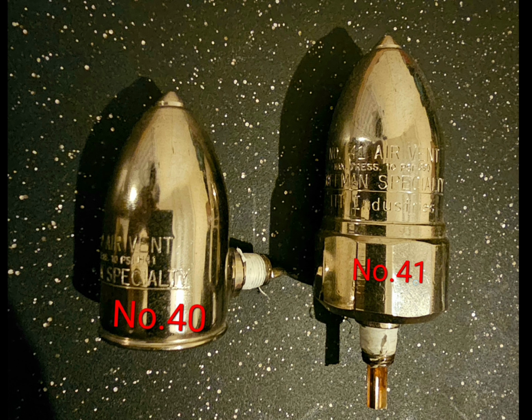The reason why I say that is because of the body of the valve. Hoffman vents are very good for radiators just based off of the body of the valve, the way it's designed. Because the temperature of the vent will fluctuate with the temperature of the radiator, which is what you want the vent to do. This is especially important when it comes to convectors that are not cast iron based.